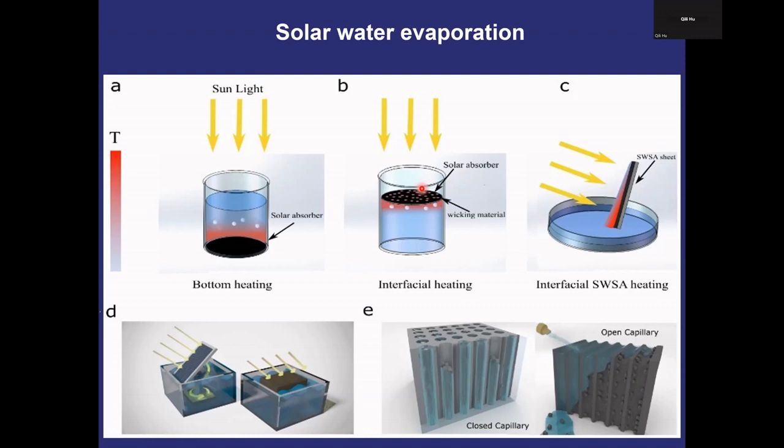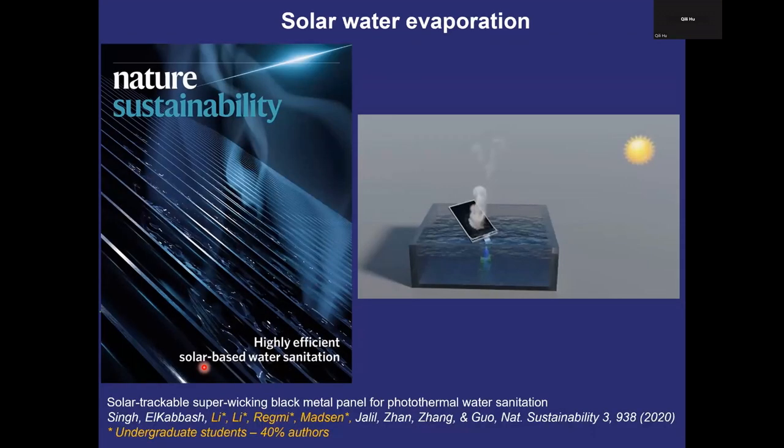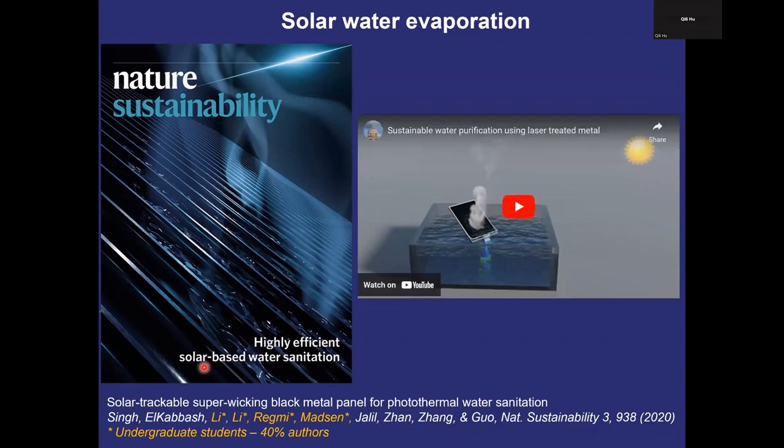And here we go. Remember, we have this superhydrophilic surface. We can pull the water uphill, and in any direction, vertical, 30 degrees, 60 degrees, we can orient it in any direction, tracking the sun's motion. So that's what we did. We have this surface constantly facing the sun, and it's black, absorbing the energy, and only wets a thin layer of water, micron thin. So we only heat up the micron-thin layer. And then here's the result. We were able to evaporate the water with ultra high efficiency.